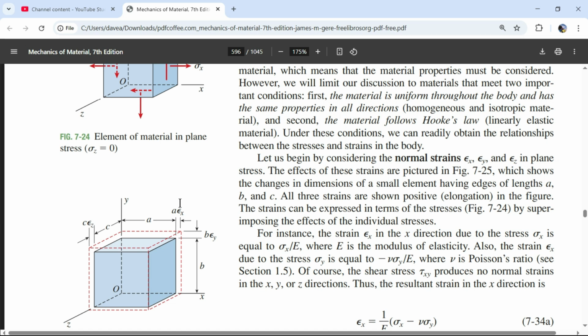That's the hardest part about strain, you're dealing with small numbers that don't really have meanings. And especially, it's a ratio. The units, people would call it unitless. I think that's a bad idea. It's a ratio of units. It's a change in length divided by length. So, because it's a change in length divided by length, if I took strain and multiplied by length, I would get the units of change in length. And if I inverted this, it would be length divided by change in length. So if I took the inversion of strain times change in length, that would give me the length of something.